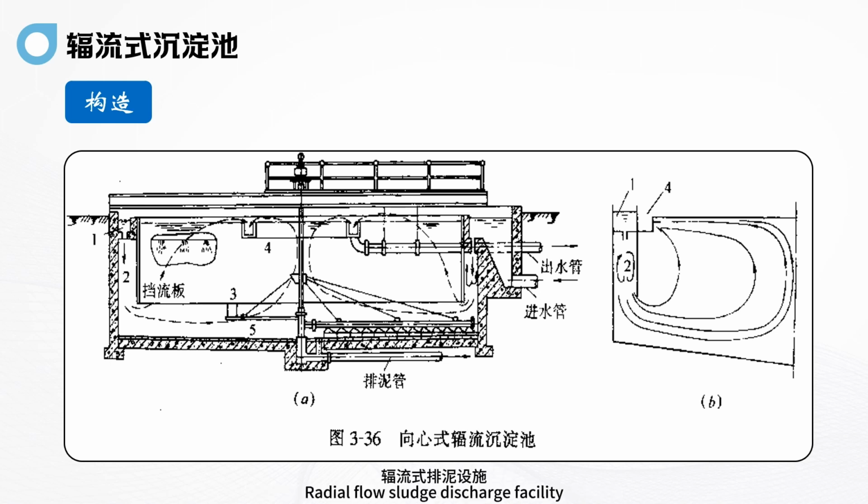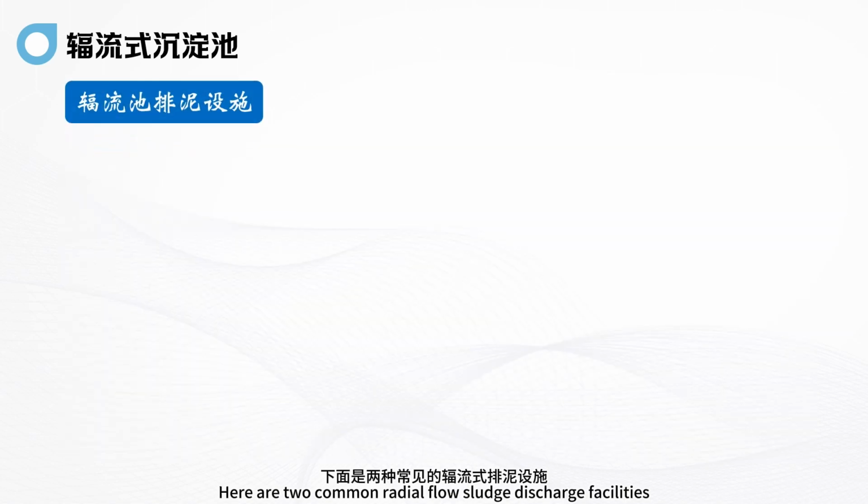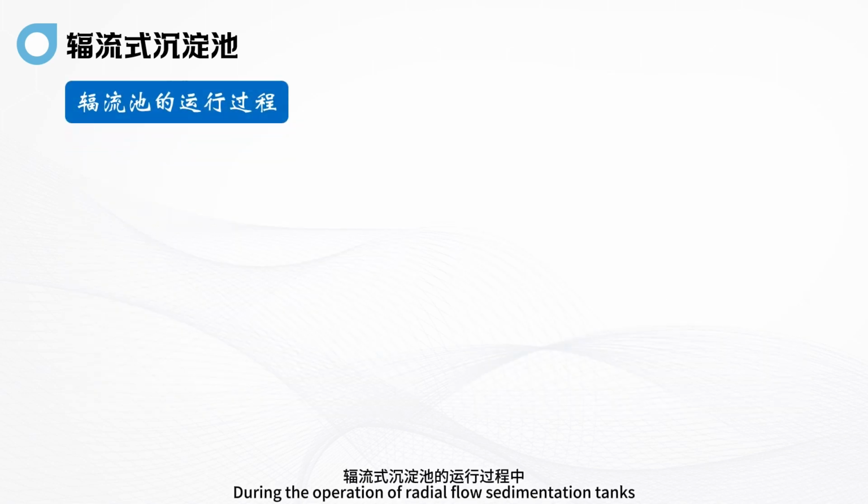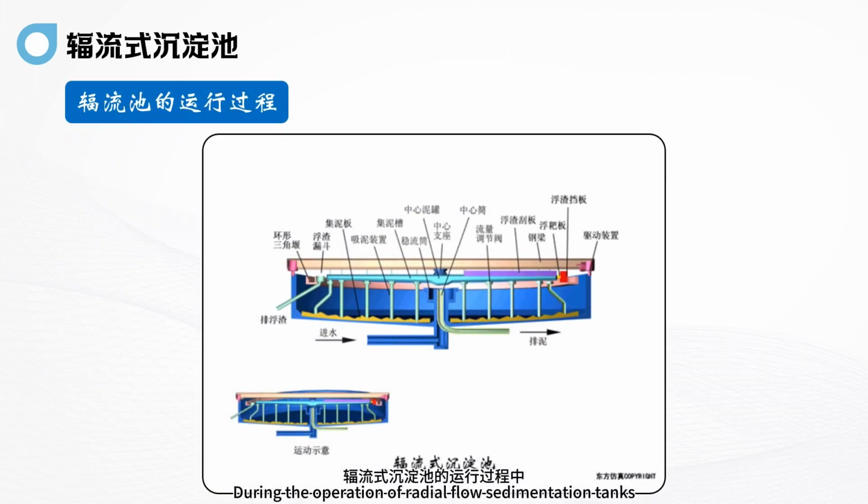Radial flow sludge discharge facilities. Here are two common ones. One is through siphoning, a sludge discharge method that does not require power. Another is through pumping, for direct sludge discharge operation. Both are relatively stable. During the operation of radial flow sedimentation tanks, with intermediate water inlet and peripheral water outlet, the operation is stable.